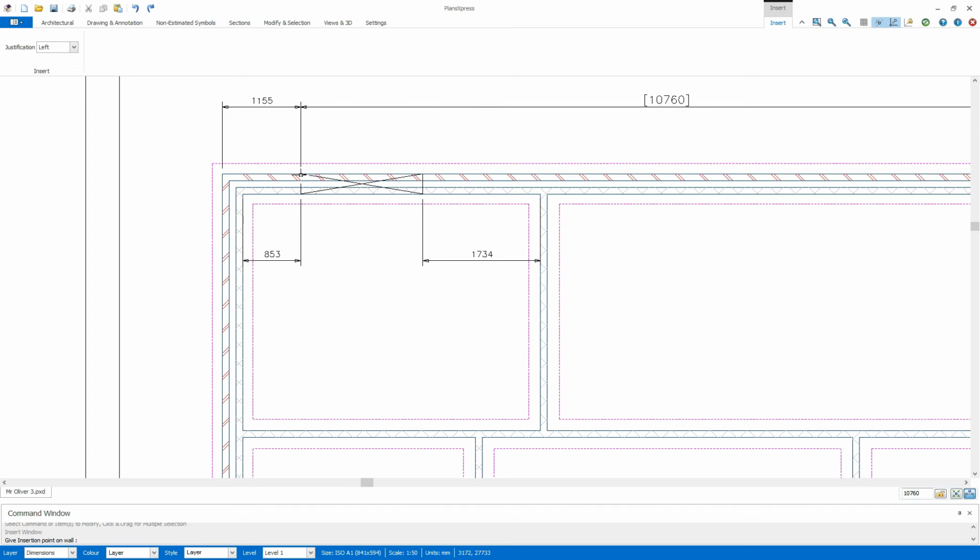You'll also see that if I move my mouse to the outer leaf, it's now measuring by that number in brackets, the external measurements, and if I move my mouse to the internal leaf, it's now measuring the internal dimensions. To change the dimension that is active, so currently it's the one on the right hand side, to change that to the measurement on the left, I just hit the tab key. So currently the correct measurement box is active, it's currently saying 1165, and it's changing whenever I move the mouse.